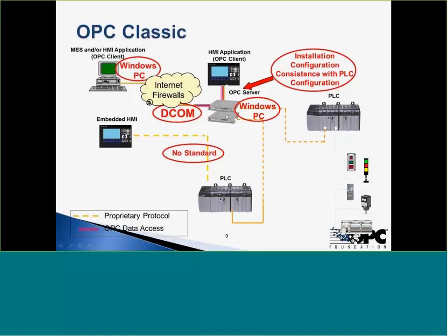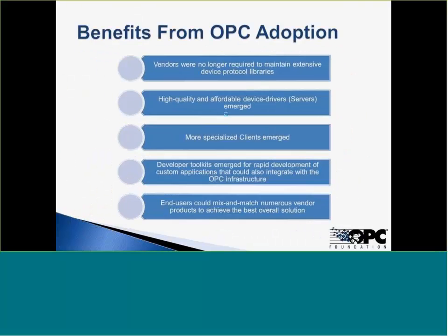We also recognized, and as InduSoft has a multitude of products that are embedded, we wanted to have a way of communicating between embedded HMIs and PLCs, and in the typical case, they weren't running a Windows PC operating system, so consequently there was no standard or no way of doing that with classic OPC. We also wanted to do PLC to PLC communication, and again, that was very complicated to do because we were so tied to the Microsoft operating system.